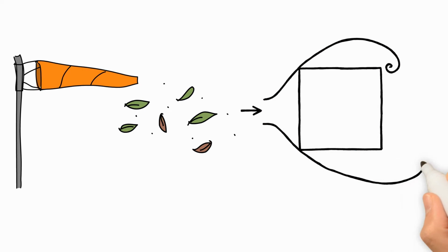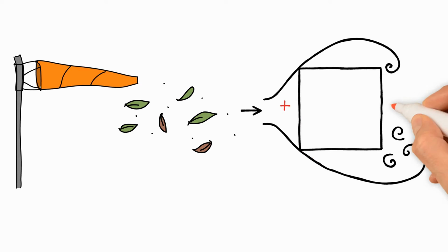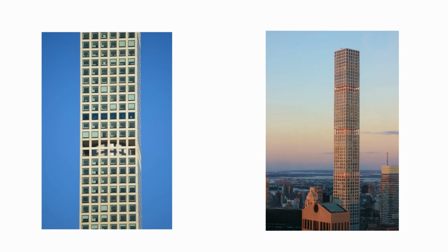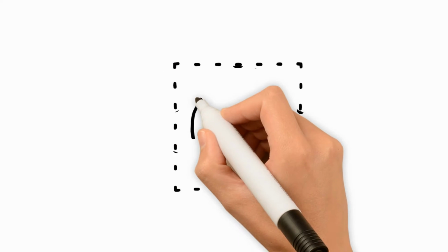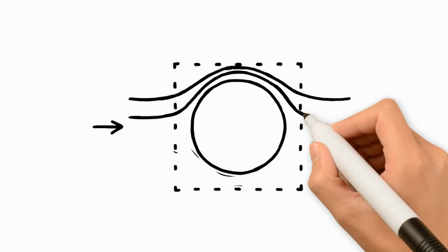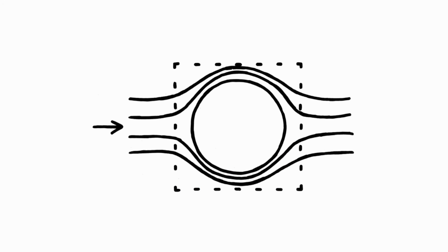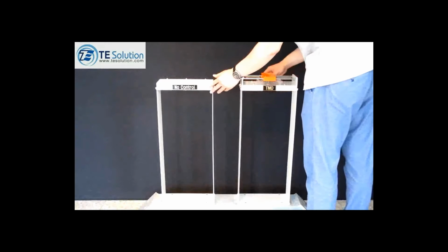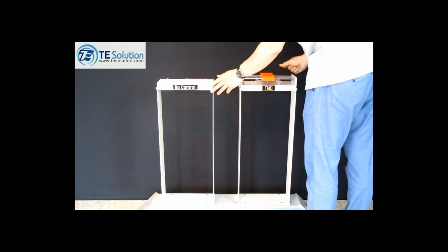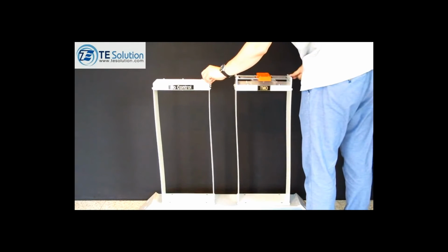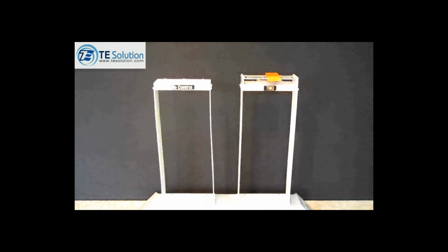This is because when wind blows around square shapes, it creates a large pressure difference that exerts large forces on the tower. To reduce this effect, 2 windowless levels were added every 12 floors to allow wind to pass through the structure. These floors are not habitable, but are used for building services. These are housed in a cylinder to further reduce the wind effects. The main issue with the wind is that it causes the tower to sway, and the resulting acceleration causes the occupants to feel uncomfortable.